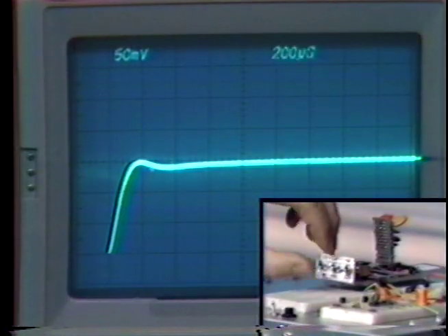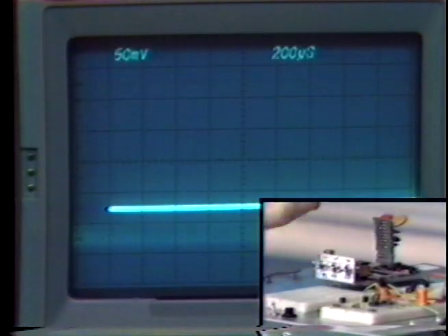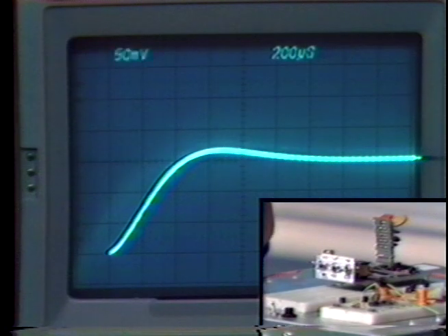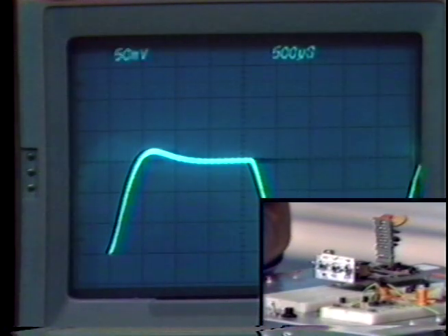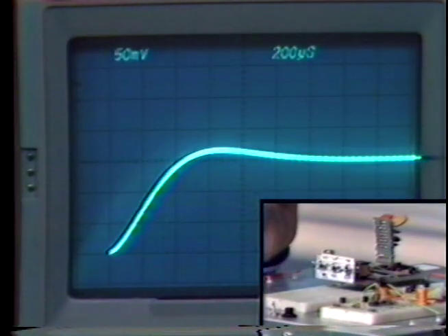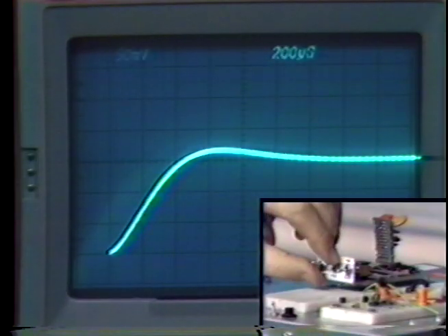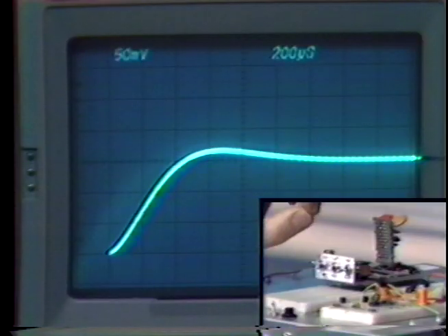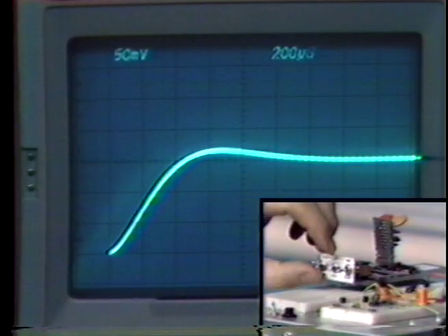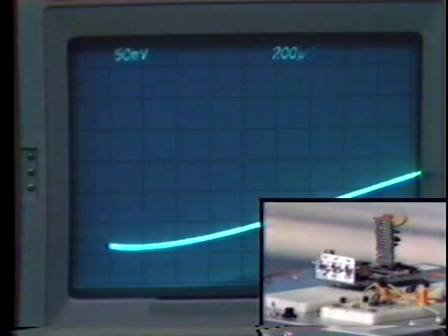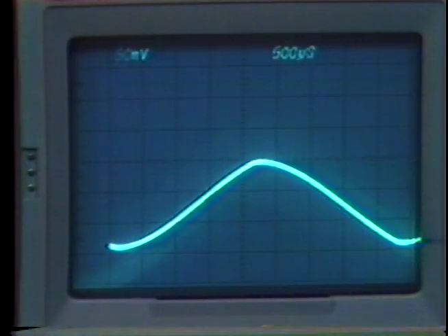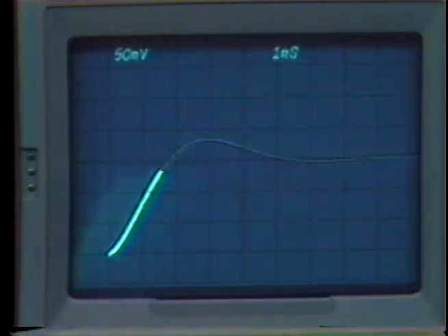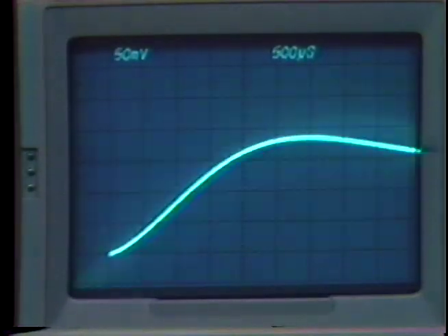Now let's go to a kilohertz rather than 10 kilohertz. OK, there we are with the network giving us a pole at 1 kilohertz. Very well-behaved response, reflecting the approximately 45 degrees of phase margin. Let's go to 100 hertz. Things get slower. In fact, much slower. But the basic shape of the response now remains almost invariant.